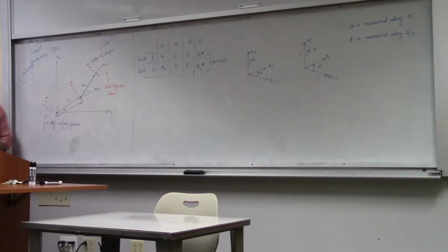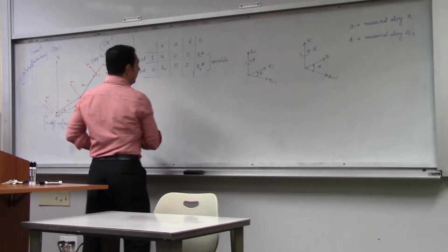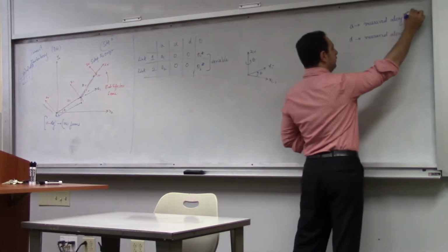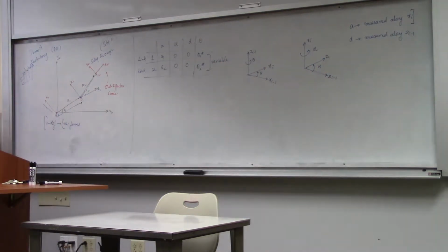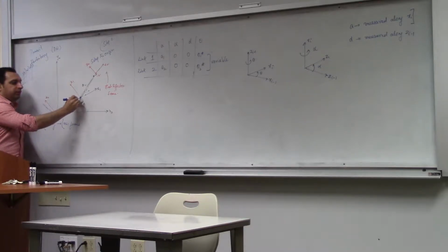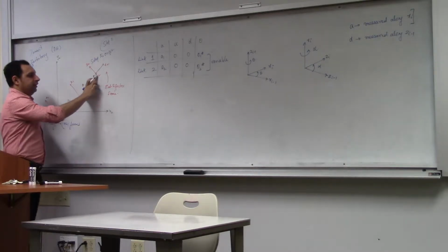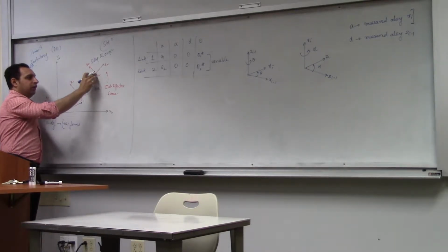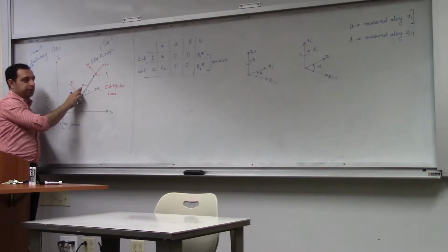I don't get it. Can you repeat it all again? Fine. So first thing is A. A is a distance measured along xi. If I want to measure A1, I'll measure the distance along x1. So x1 is measured from this origin all the way till it intersects with z naught, the previous z-axis. This distance is A1. Same thing here: you start from this origin, move along x2 till it intersects with the previous z-axis, which is z1. This is A2.